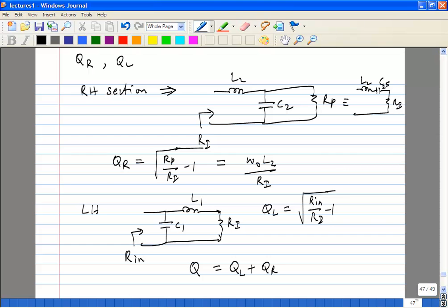Similarly, if you put in 200 ohms on the other side and look in left, you will find Ri, when it's perfectly matched. Remember, Ri is not a real impedance. It is just some kind of circuit impedance at that portion of the network. So that is the reason why we applied that condition, because if you had a real network that was well matched, then you would have that case.